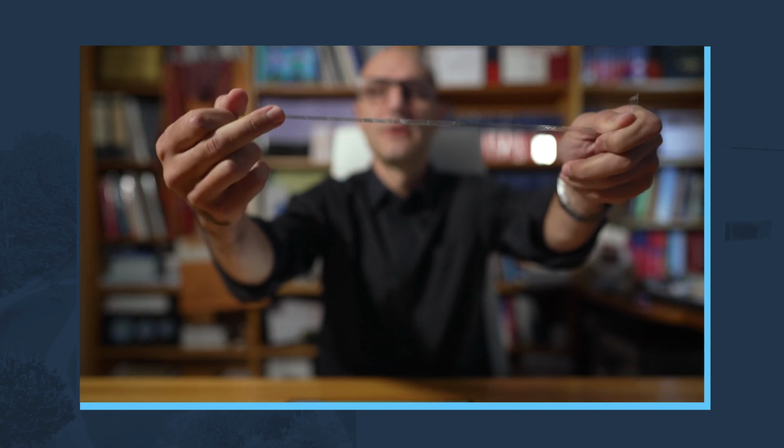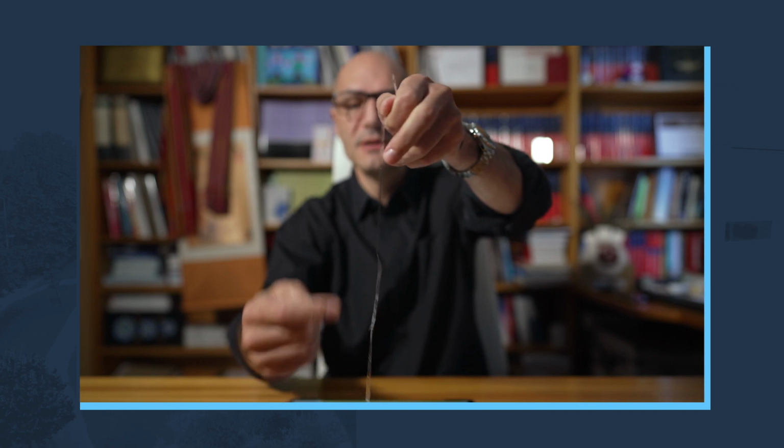And now I'm going to load it like this. So the substrate will be tensile loaded, but the adhesive will be shear loaded. And the resistant area for the adhesive is quite long. It's the overlap times the width. Okay, overlap times the width. Huge resistant area. Whereas for the substrate, it's very thin, the thickness times the width.